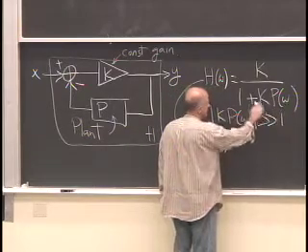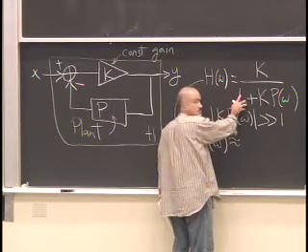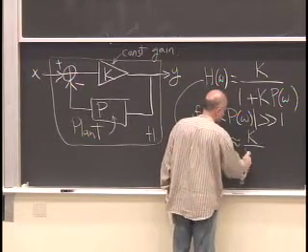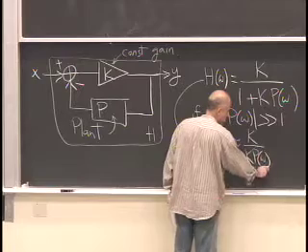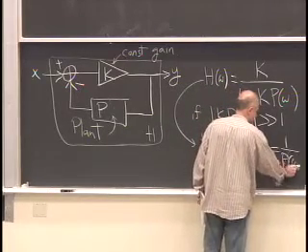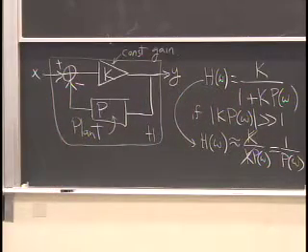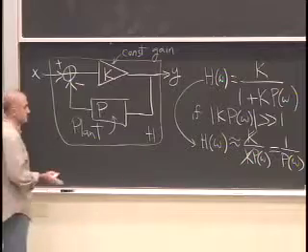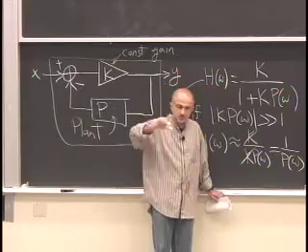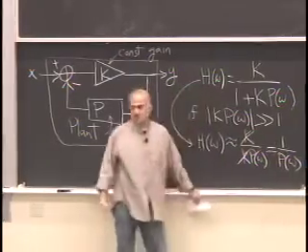So take me through the steps. This is much greater than 1. So what do you do with the 1? Get rid of it. So you're left with K over Kp. And then the K's cancel. So you've approximated an inverse system. Okay? Not exact, but we usually have in the real world some tolerance for going away from the ideal. As long as it's a good enough approximation, we're happy.